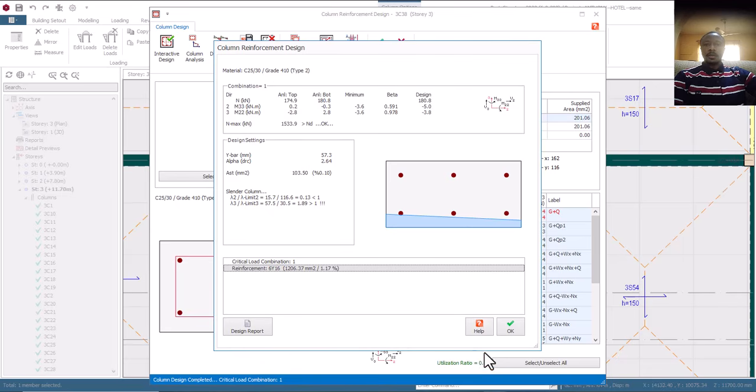And secondly, or thirdly, whatever it is, you can now see your utilization ratio. You know that based on our interactive design principle, our utilization ratio should not be greater than 1, or should not be up to 1 rather. Everything should be 0.9 or below. If you now look at this one, this is 0.19, not even 0.9, not even 0.8, not even 0.6. This is 0.19. Can you see it now? Which is far from 0.9.